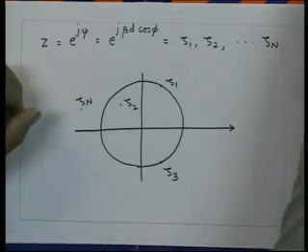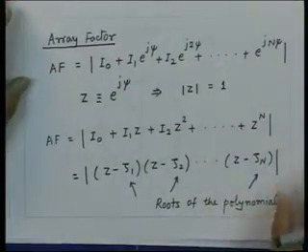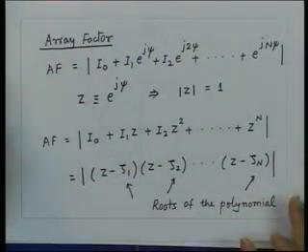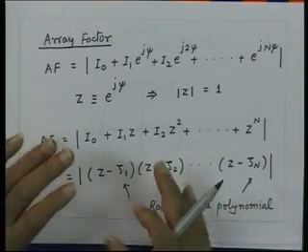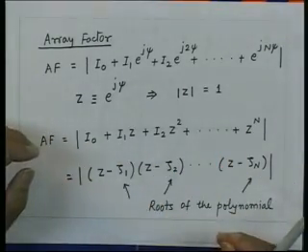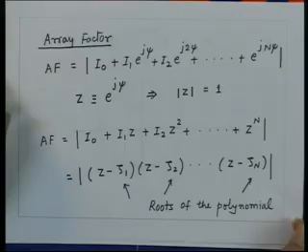Now, although the theorem says that every polynomial can be thought of as an array, and every array represents essentially a radiation pattern and a polynomial, the root of a polynomial does not necessarily represent the null of the radiation pattern, because for the null to be represented, the points should lie on the unit circle.